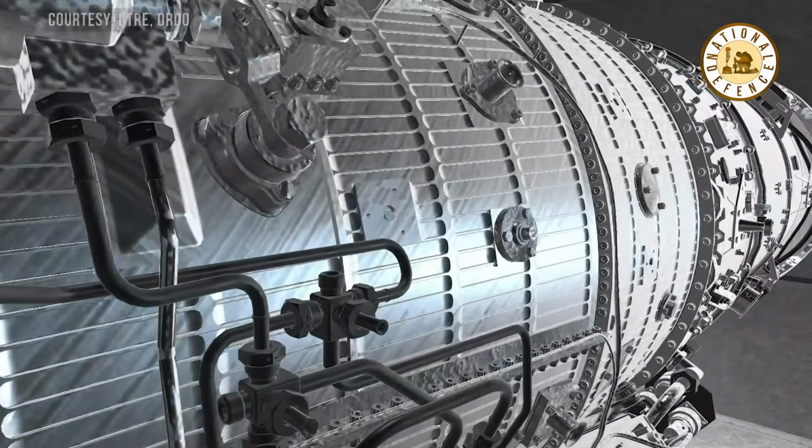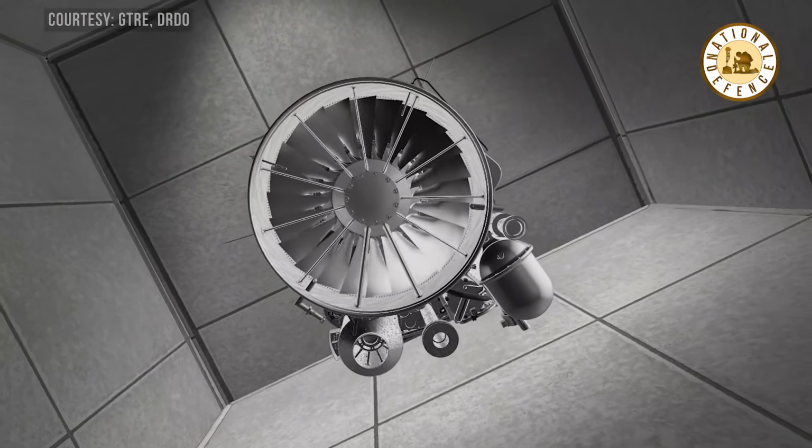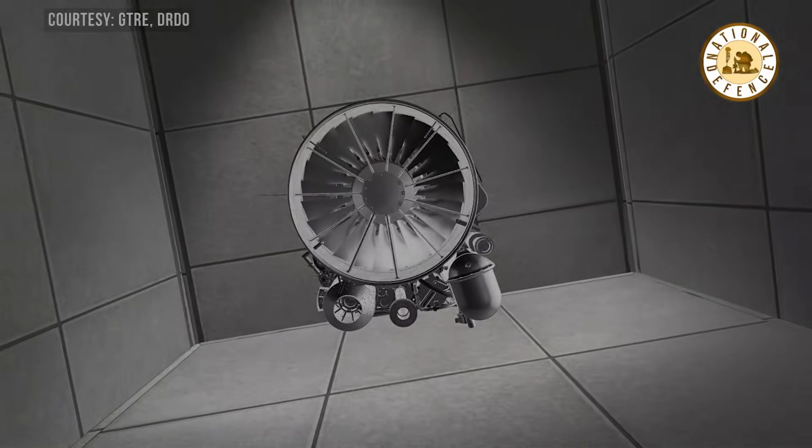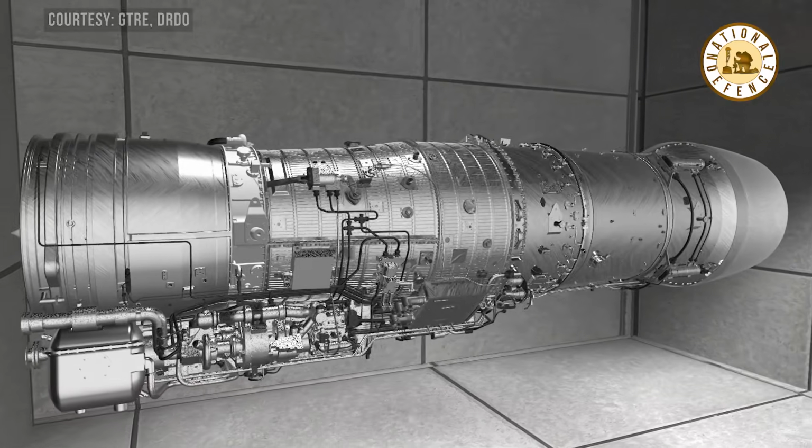Second thing is how to reduce the weight design-wise itself. For example, we are going for the blisk. Generally the blades are assembled to the disc, and there are retaining plates, or they are bolted. It causes higher weight, higher losses. Whereas the bladed disc is a single component. Say 73 blades and one disc will be only a single component. 25% of the weight can come down by using the blisk for the blade plus the disc. And the reliability also will increase because it is only one part now. So that is regarding the blisk technology.